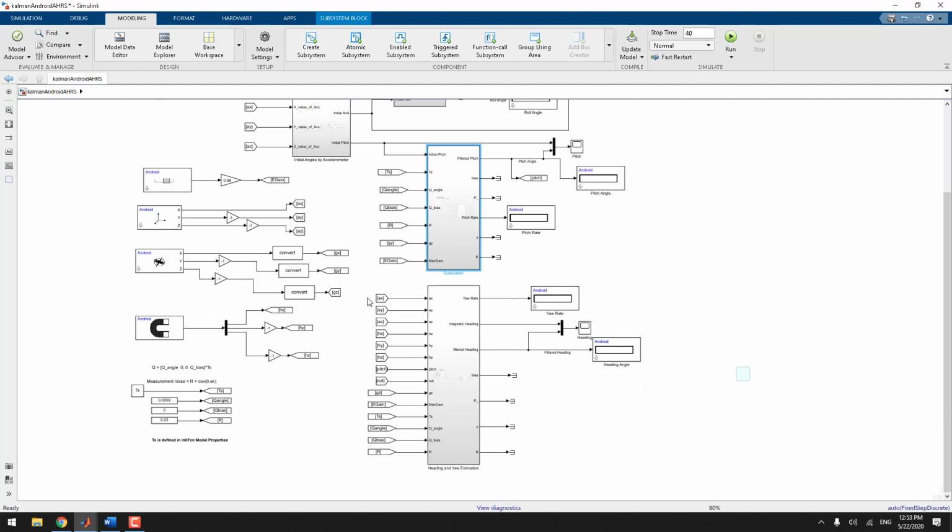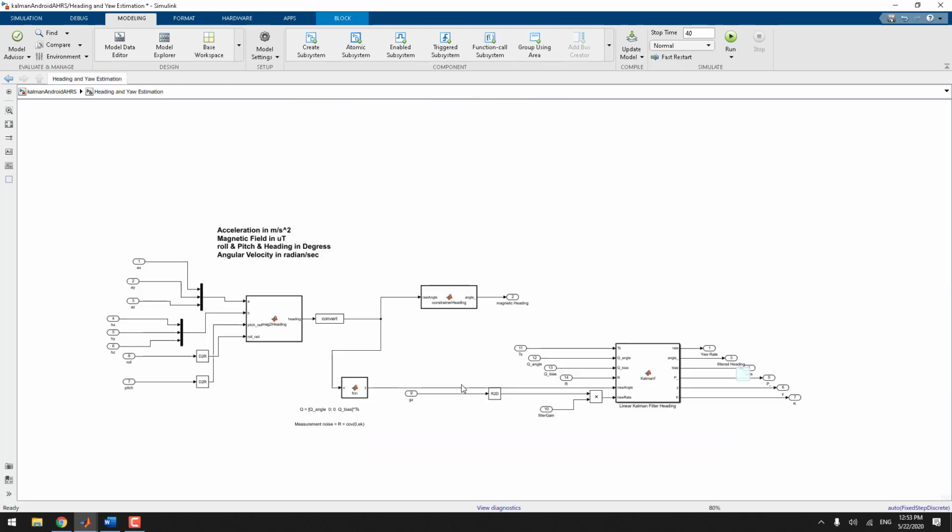The difference is that we are going to use the gyro around the y-axis, and for the z-axis it's a little different because we cannot have an initial guess for the heading or yaw based on the accelerometer. So the initial guess is based on the magnetometer, and then we combine it with G of z, so the gyro around the z-axis. Again, everything is the same here.